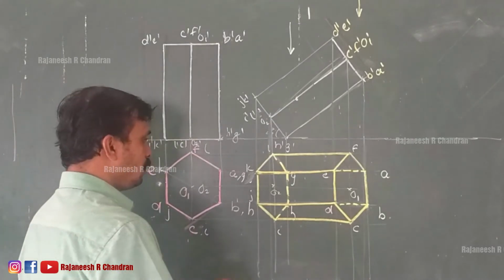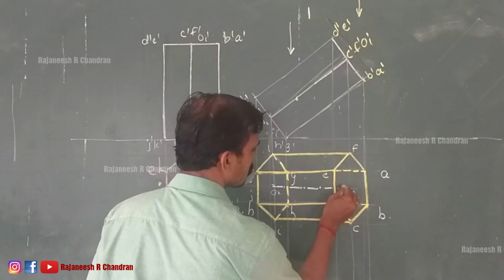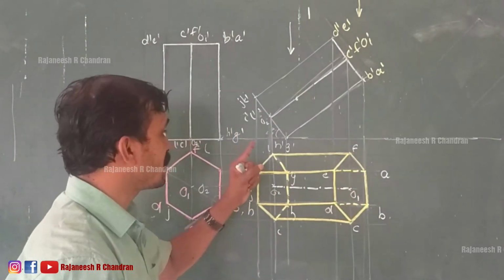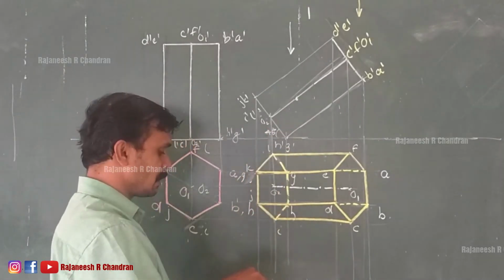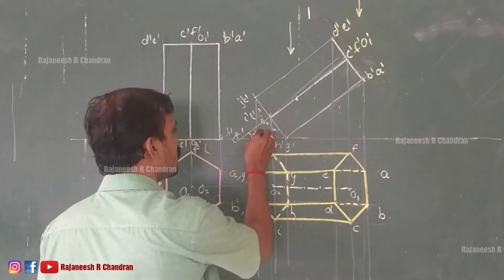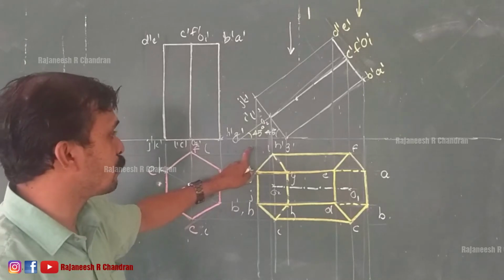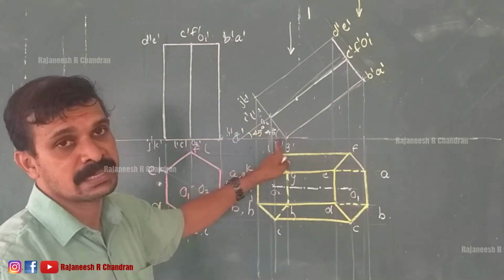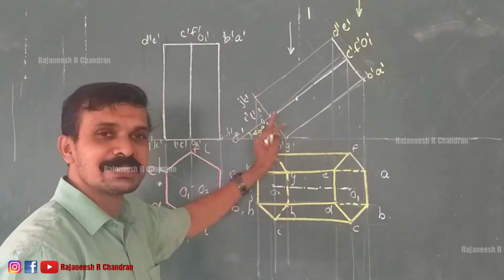Now this is our axis. So the axis is also marked. So now the first inclination, that means the axis is inclined at an angle of 45 degree, has been completed. See, this is the axis, so that dimension also needs to be given. Since the axis is inclined at 45 degree, what we have done is the base inclined at an angle of 45 degree. So I hope all of you understood this much portion.